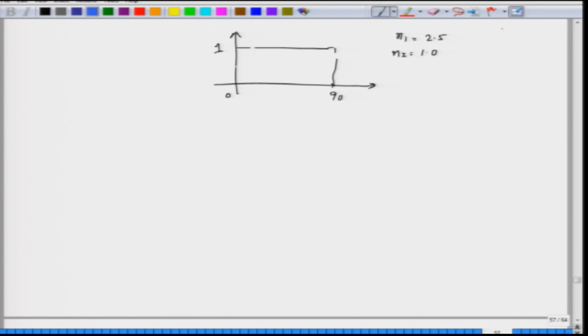You look at this, it starts off somewhat close to 0.5 or 0.43, maybe even slightly different than that, let us not worry about that. However, as you start increasing the angle of incidence, it drops down at some angle, 22 degrees, which would correspond to the Brewster angle. The magnitude of Tm will be equal to 0 at this Brewster angle. However, after a slight change in the angle, the reflection coefficient suddenly becomes 1 and then remains 1 throughout the rest of the incidence angle.